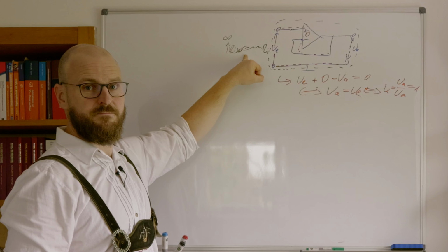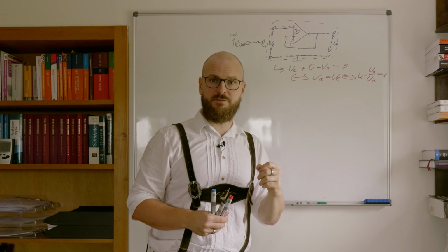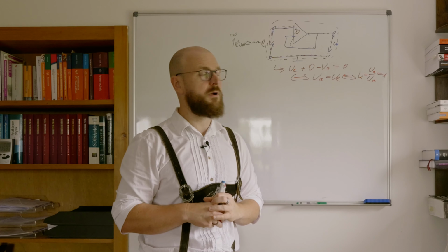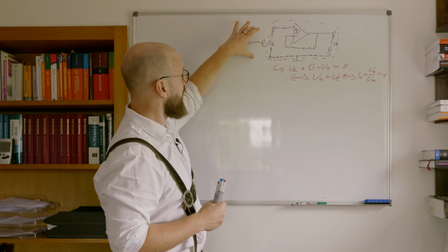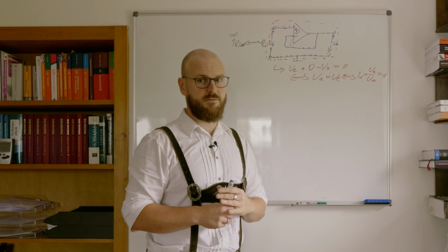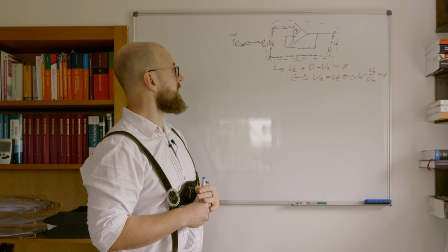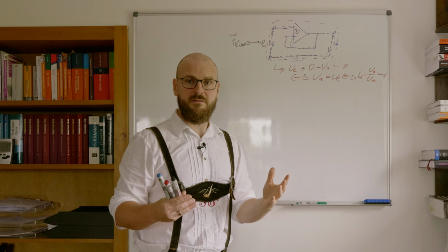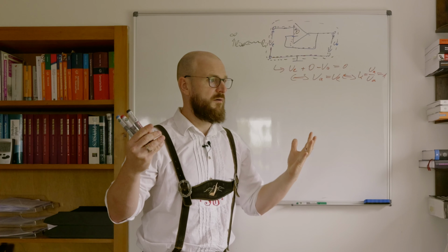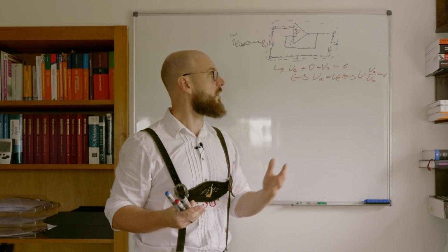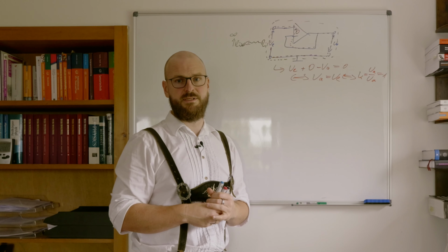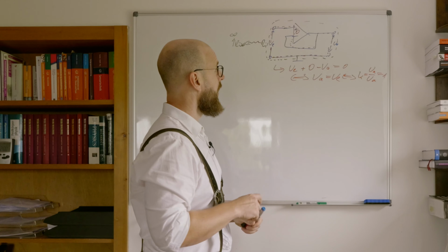That's awesome. Think about photodiodes, which have resistances between 1 mega ohm and nearly 0 ohm. We now have a system we can just connect to such a photodiode or a photoresistor, and taking that voltage, not having to deal with the high resistance of the photoresistor when it's dark, because that thing has an even higher input resistance. Great.